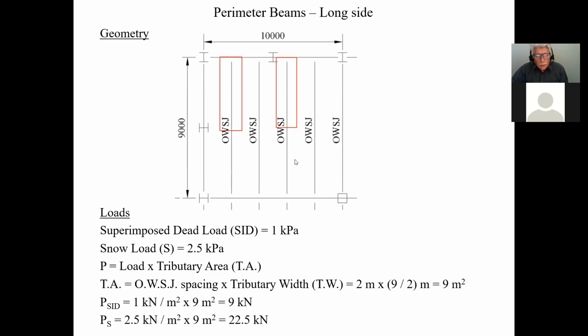And now that we have this, in other words, all you have to worry about is making sure you apply these 2 forces along this member here. And of course, 2 meters, 4 meters, 6 meters, 8 meters. You'll notice I really don't care about the loads coming here because that's going to get supported by the column. I don't care about the load that's going to get supported by the column. So the only ones that are going to be affecting the forces in the beam are these 4, and therefore I'm only going to worry about applying these 4 forces.